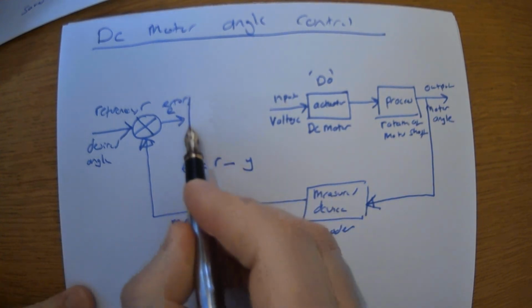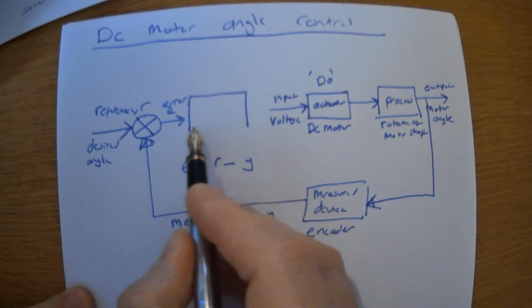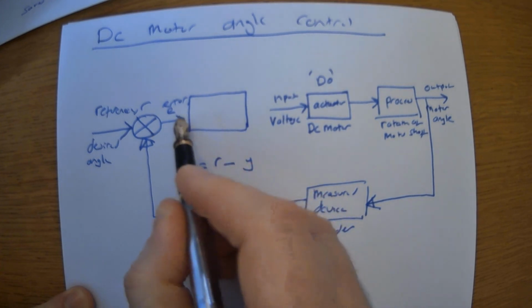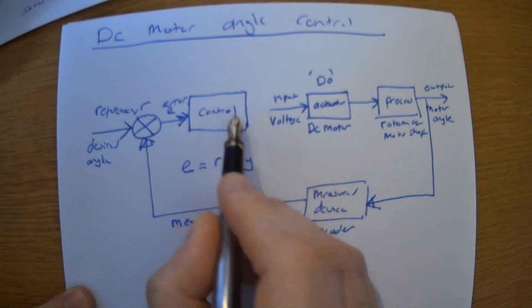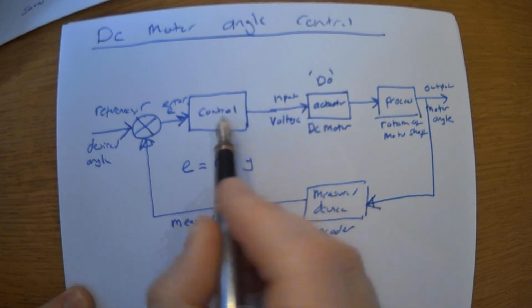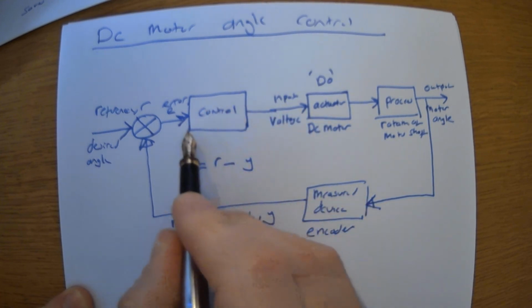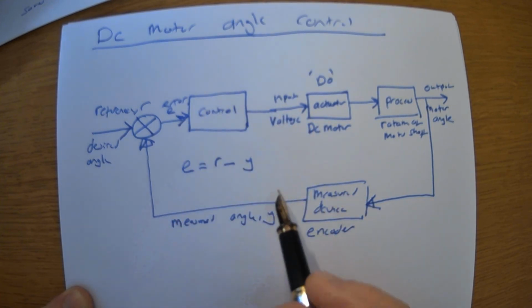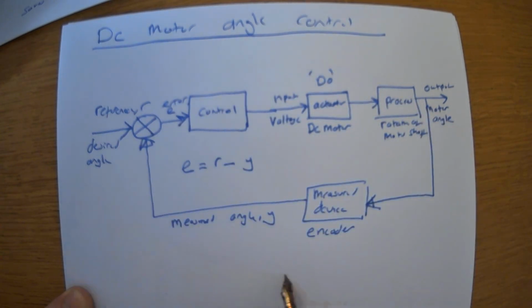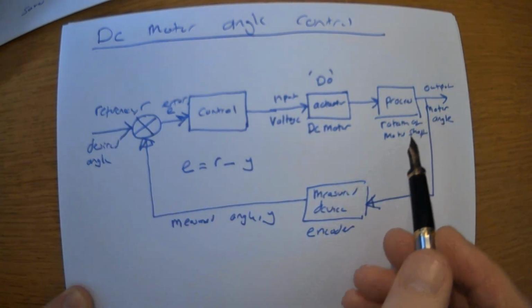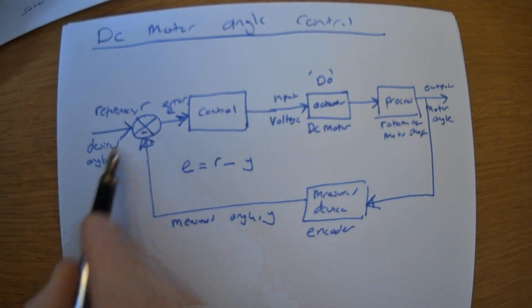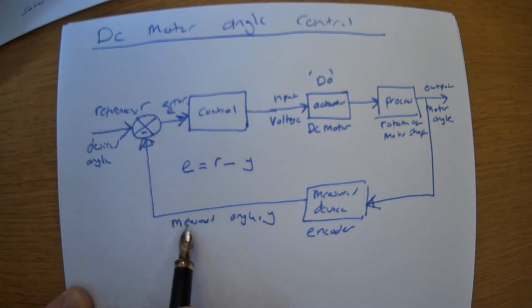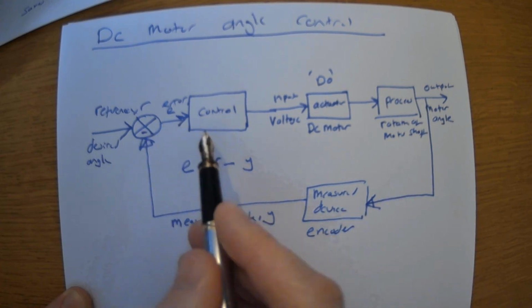And the error signal is effectively used for the control action. So here, the control. You're going to become more aware of this as we go week by week, all the different components and how this all works. So what we need in there, just remember, is a negative, because it's reference subtract the measured angle, and this here being your feedback loop.